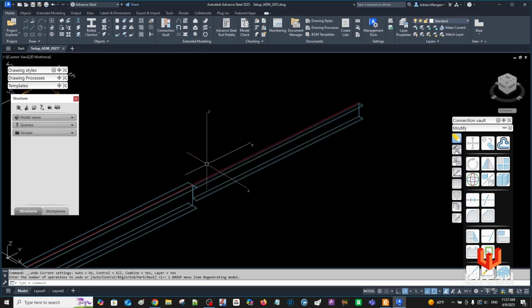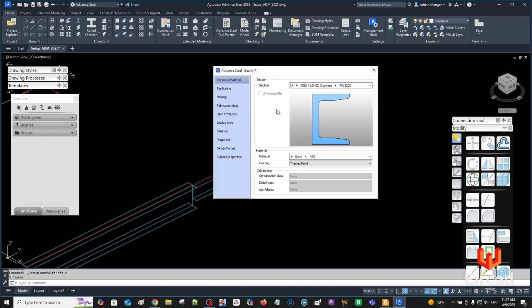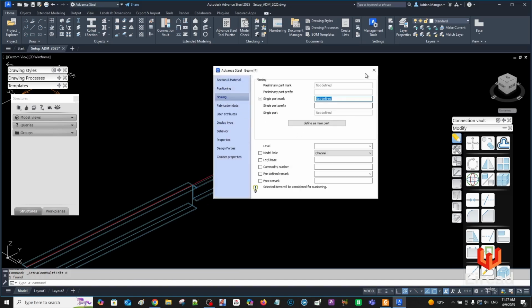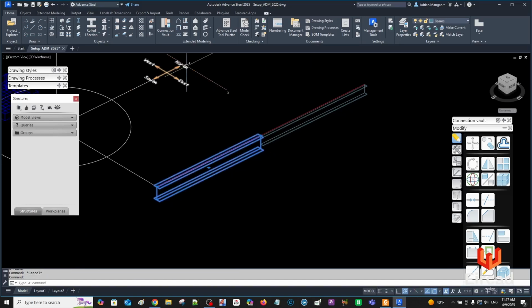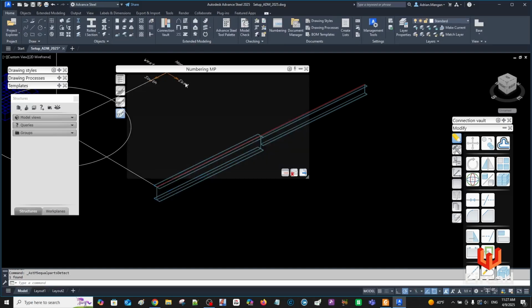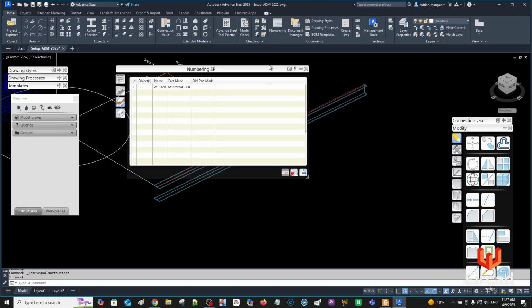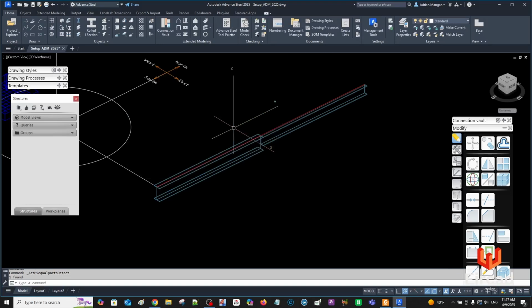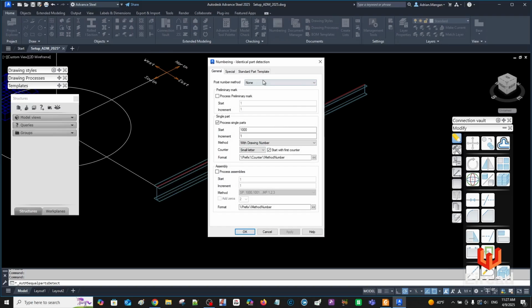Equal parts detected. Once you go past the equal parts detected, that usually means the numbering has gone away. So there, the numbering is gone. So if I number this beam now, it'll be B1. No, it's going to be, right. So what happened there is I'm going back now, my numbering, I didn't update the numbering because I backed through what I had set up. So when I undid whatever I set in here, I'm going to go back in and set this again.